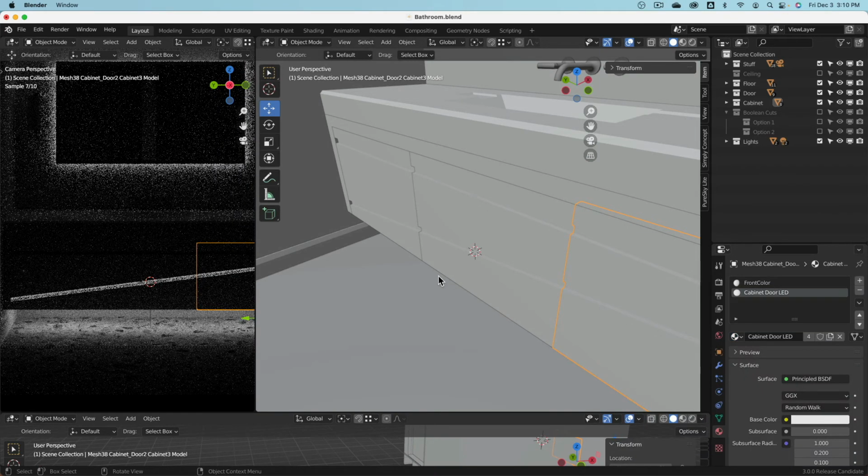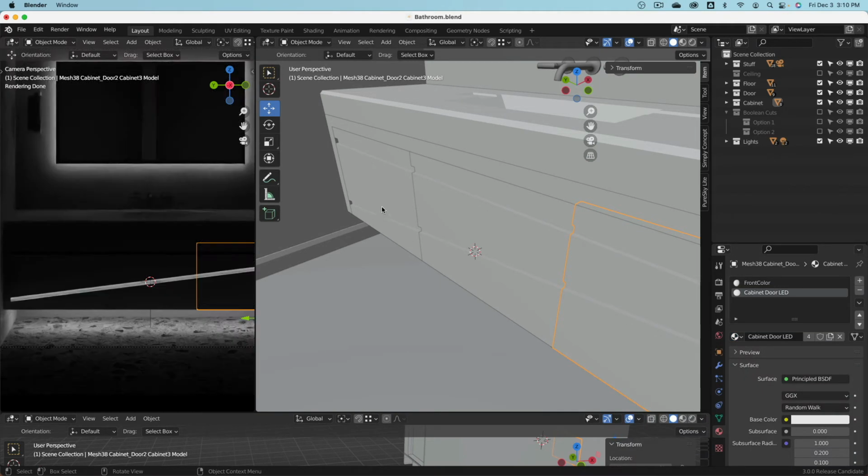So what's happening is that this object has this color. And then we cut it via this small strip. And then we give this door also this LED material, but we don't assign it actively to something. Because the way Blender works, it removes geometry via the Boolean command, and where it cuts, it can also add the material to it.